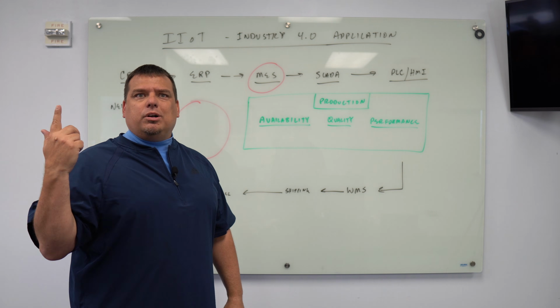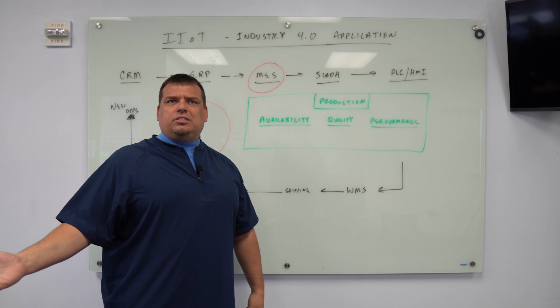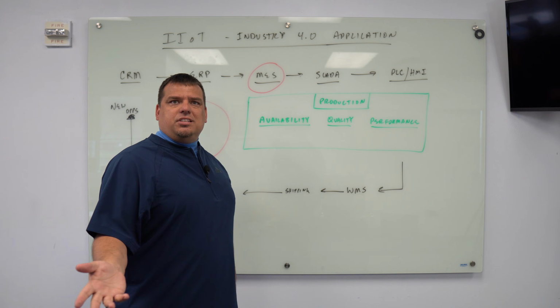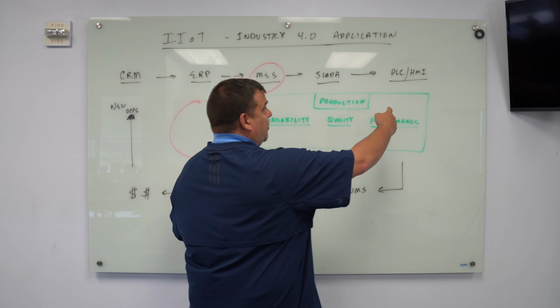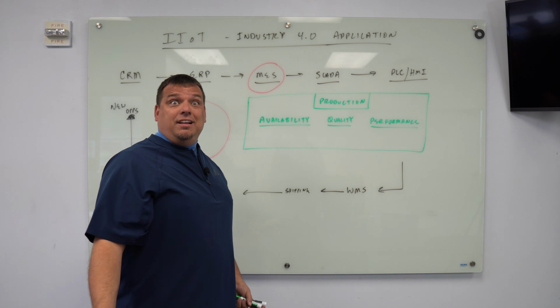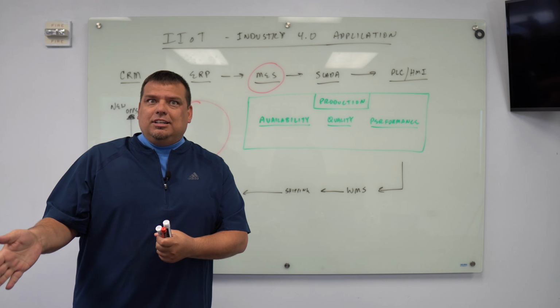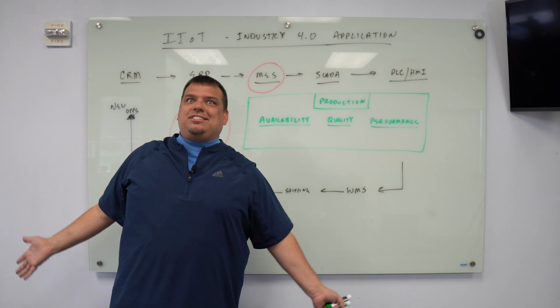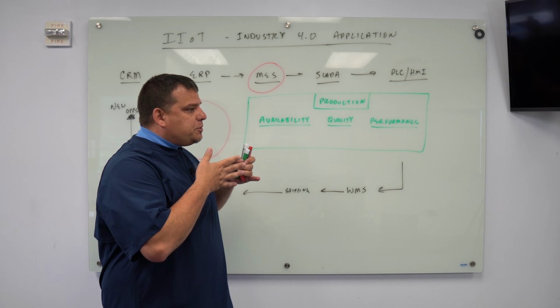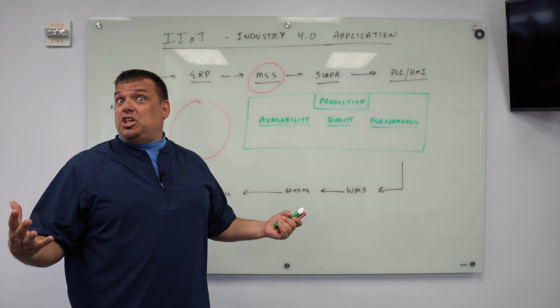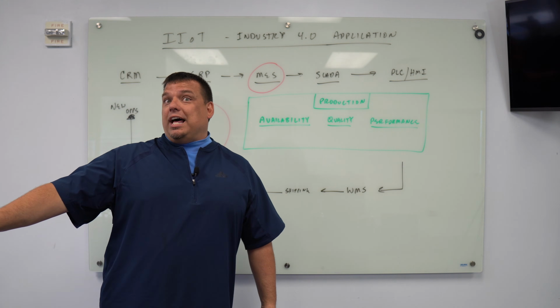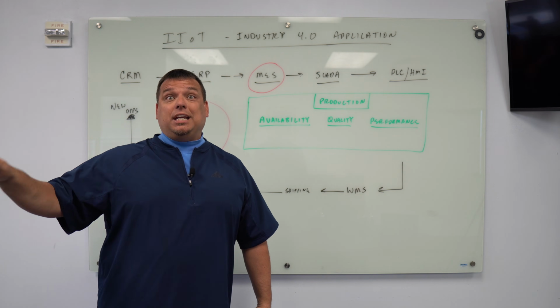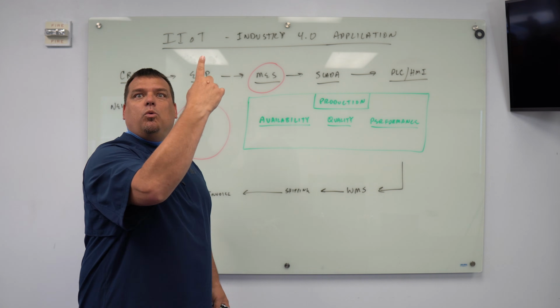You want to know what your number one risk of connecting your business network to your process network is? It's multicast traffic. Everything out here is explicit unicast transmission. That is, the HMI talks directly to the PLC. It doesn't broadcast out onto the network. It talks explicitly to the PLC and doesn't generate a lot of noise. Therefore, the PLC doesn't spend a whole lot of time trying to decipher messages it should be ignoring. That's your number one issue.